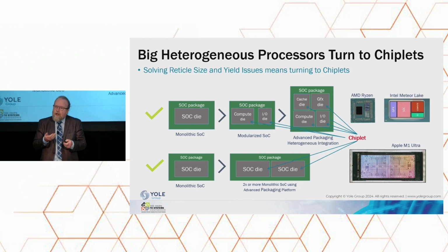Then there's also taking functionally smaller, or what is typically a very complex heterogeneous die, in a smaller package that will still fit into a reticle and actually mirror that heterogeneous solution connected by an interposer or connected onto a substrate as one die or one processor solution, as we have an example here from the Apple M series.